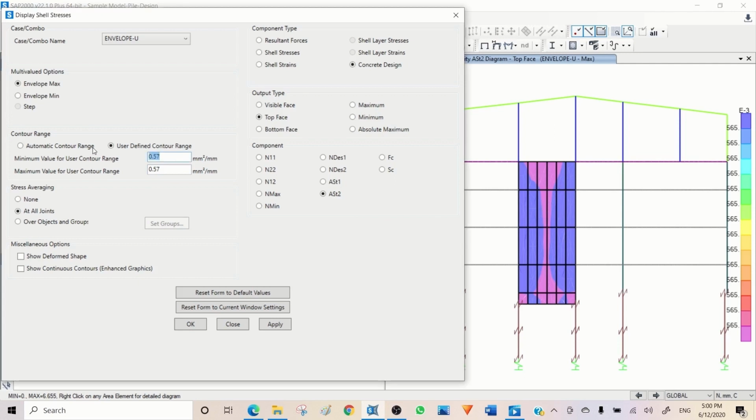If I go for N16 at 200, the ratio would be 1, which is 1000 square millimeter per meter. So if I press apply, it shows me less area where I need more reinforcement. I may add some extra bars here and strengthen the corners, and then N16 at 200 probably would be acceptable.